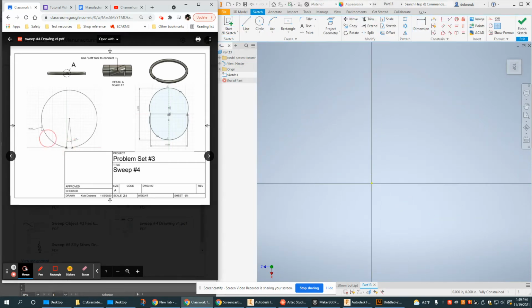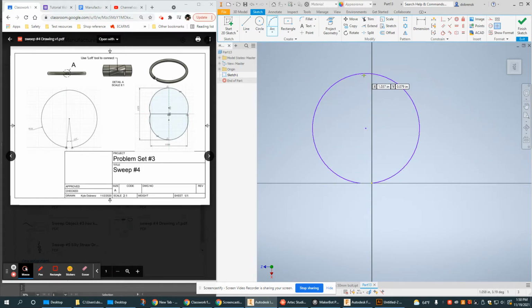And this is not quite a circle. This is just a nearly complete arc. And if you read here, it's 12 degrees from full 360. So here's my two endpoints. And I always like putting one endpoint of my path on the origin. It just makes life easy when I can use existing origin planes instead of creating my own work plane.